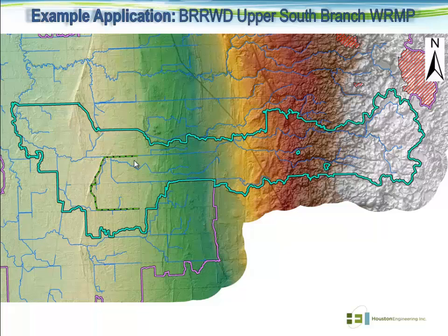If we get into flat topography, a very low embankment height will back water up for a very long distance. So there's kind of a preferred region, which is kind of at the base of that beach ridge I was talking about, to place retention sites.